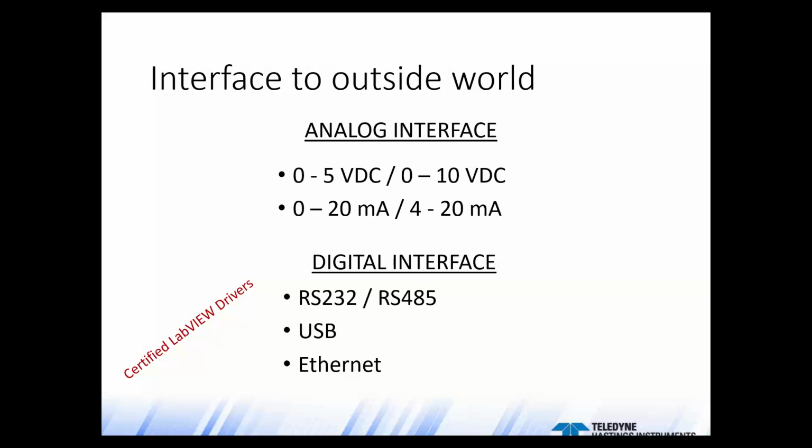You may also want to consider going strictly digital I/O via RS-232 or RS-485. We also have USB serial or Ethernet. Now, one of the advantages with the digital approach is that you can use our free software or you can use our free certified LabVIEW drivers. There's also an added benefit because with digital, there's no uncertainty in the steps going from the D to A to the A to D conversion with the signals.